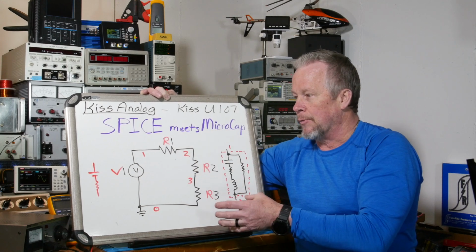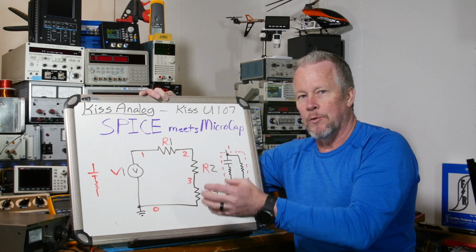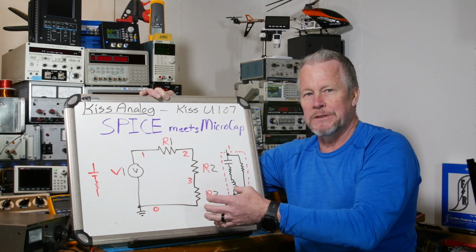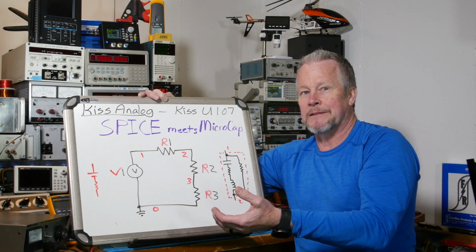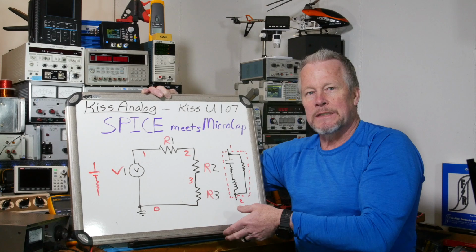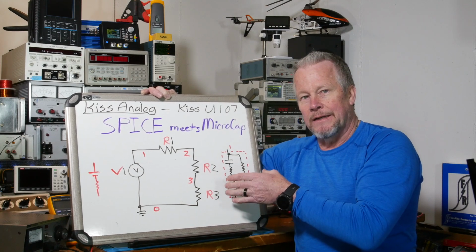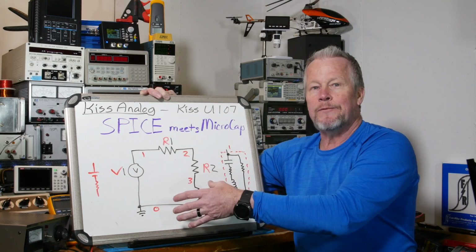Understanding your circuit and how it works, understanding the parasitics and where they come from and which ones matter at a certain time, which ones don't. Sometimes you get surprised. You go, ah, geez, I didn't realize that inductance or the capacitance was going to throw me off. So that's why sometimes the bench work looks different than simulation.